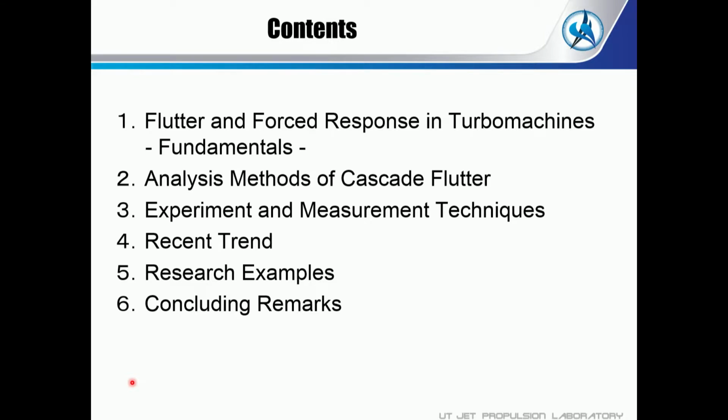Okay, so from today, in this 3-day course, I'd like to talk about Flutter, mainly Flutter, its aeroelastic problems. But in the so-called flow-induced vibration, we categorize the phenomena into Flutter and force response. This lecture is mainly on Flutter, but I will briefly touch on force response later. The first topic is the fundamentals of Flutter and force response in turbomachines.